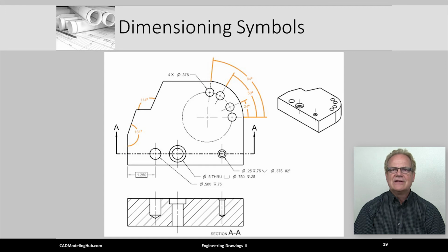This slide has 5 highlighted angular dimensions. While most angular dimensions you will create use extension lines, sometimes it is okay to use the object lines of the part to limit the angular dimension.